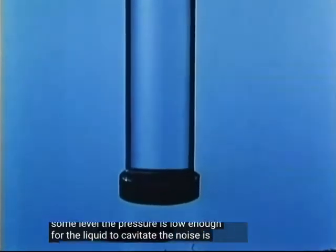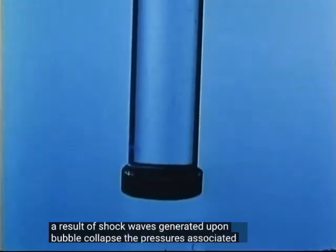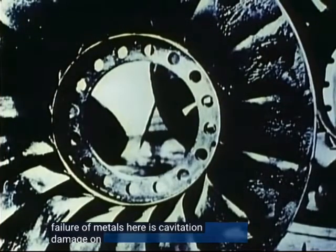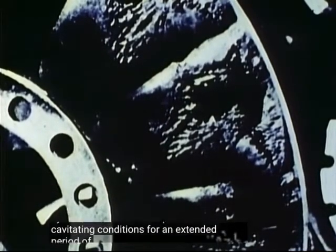The noise is a result of shock waves generated upon bubble collapse. The pressures associated with collapse are high enough to cause failure of metals. Here is cavitation damage on the runner of a large hydraulic turbine, which operated under cavitating conditions for an extended period of time.